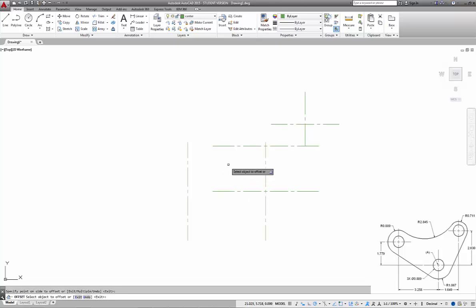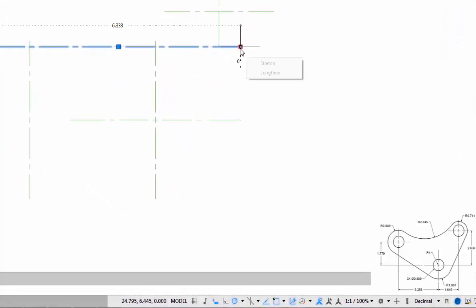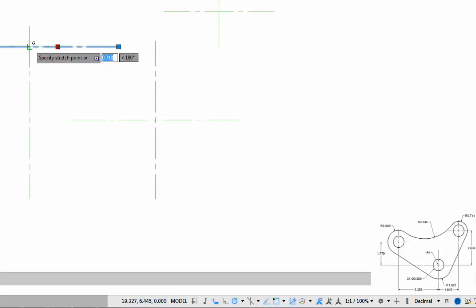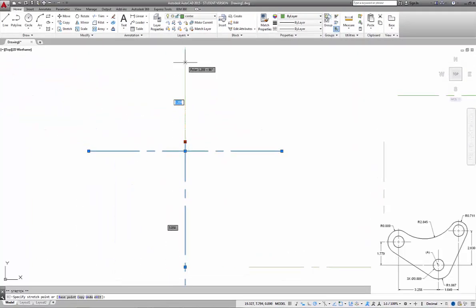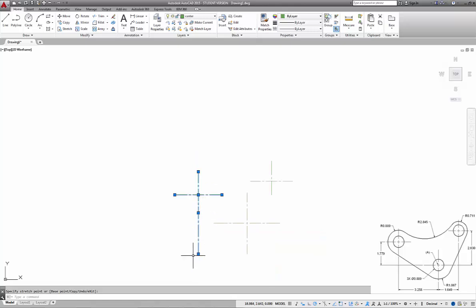So it's a good idea to get into the practice of using layouts, of using center lines to get started with your drawing environment. And it'll just make life so much easier than just creating it blindly. So again, using the grip tools, I stretched it and moved and manipulated. And now I've got 3 center locations, which are the 3 center points for all my circles.